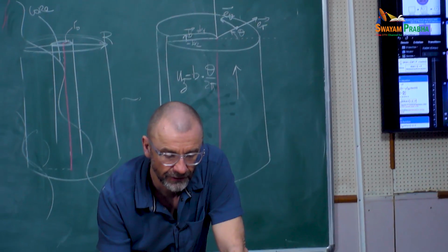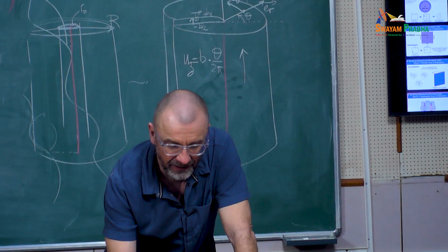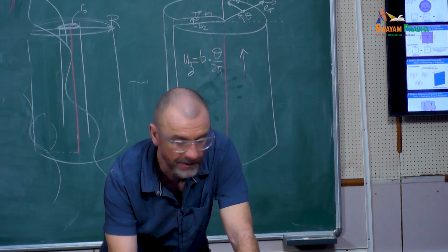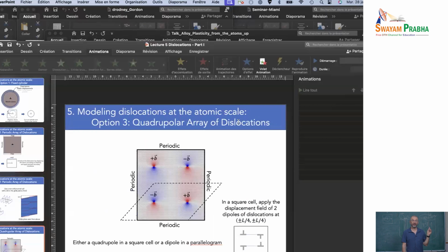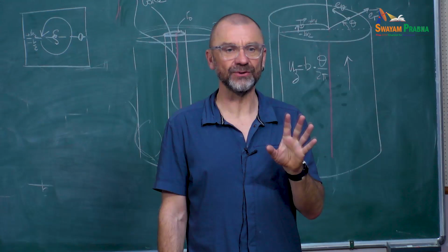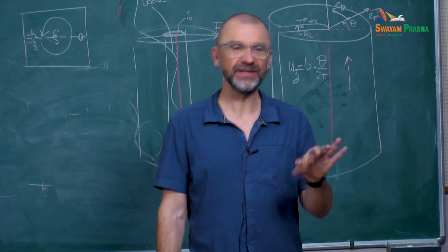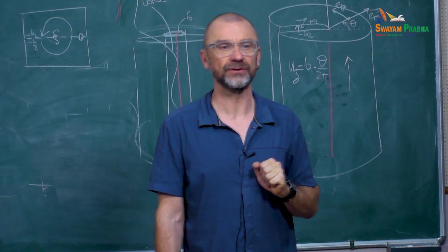In an ionic system, if I use PAD, then on top and bottom here, I'm going to create charged surfaces, and that's bad for the calculation. So with ionic systems, it's much better to use a dipole, because then you don't have these free surfaces. So depending on what you want to do, you can choose any one of the three options.